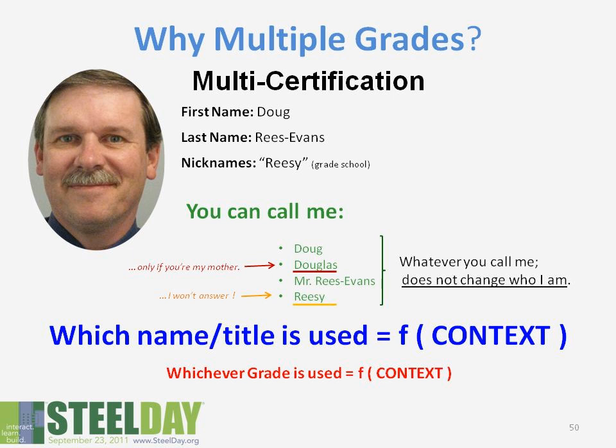It's the same with our steel grades. The analysis doesn't change what it is. That is what it is. The grade is what context is it intended to be used in. So if I multi-cert something, it can be used in an application someone's designed for A36, yes. If I certify it as A709 and I certify it as 992, then yes, it can be used in highway work because it meets those requirements, or it can be used in general structural applications.